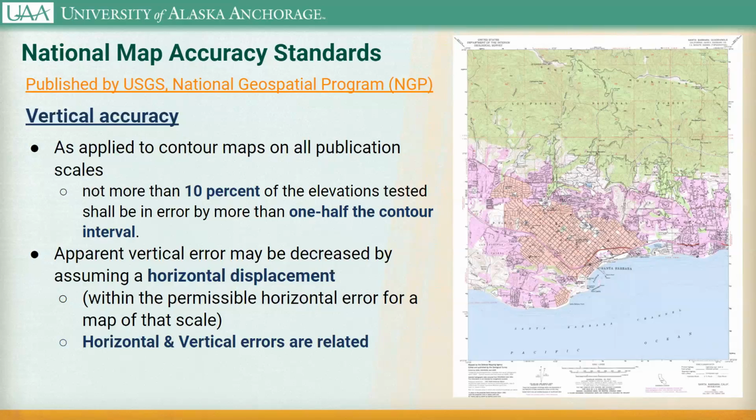That way, if you have known elevation points sliding around on your map because your map is not accurately placed horizontally, sometimes that's identified through a vertical problem. And you can often see that when you place 2 different data sets over each other. It might look like one of them has an elevation shift when it's actually a horizontal shift.